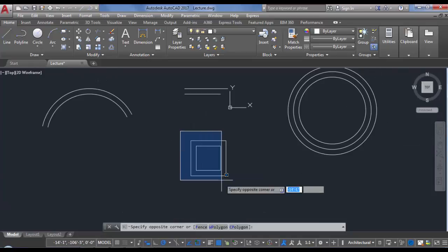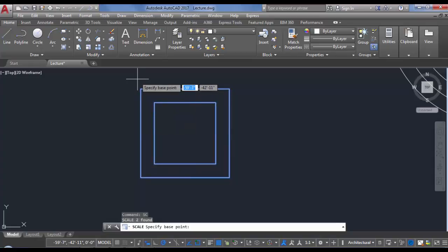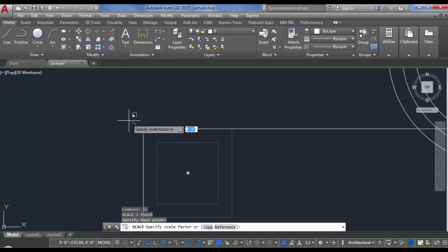Now similarly, if I want to scale this room, or whatever figure I have made, considering this is a room or a box or just simply two rectangles, whatever you want. Just like that one, I have typed scale, then I'll be typing how much. Say now if I want to reduce this, I don't want to increase the size of this one. Last time with the line I increased 20%, so this time I'll be reducing 20%. That means I'll be using only 80% of the figure, so I'll be writing 0.8.